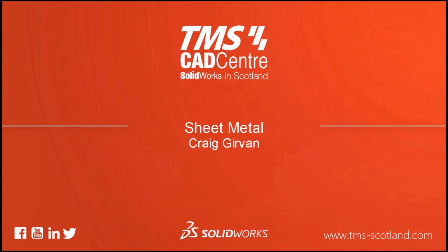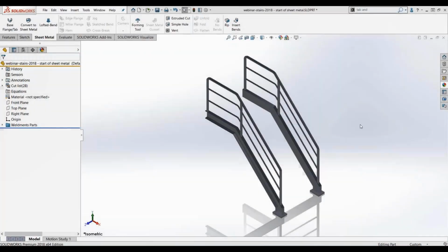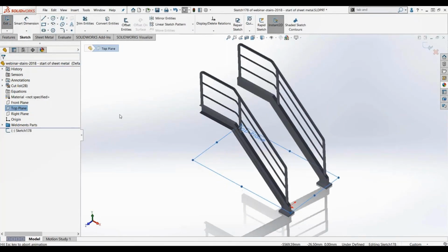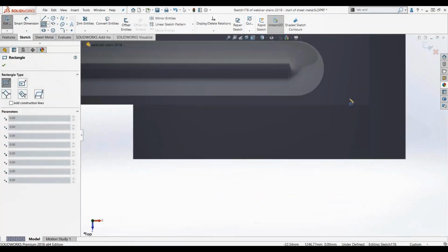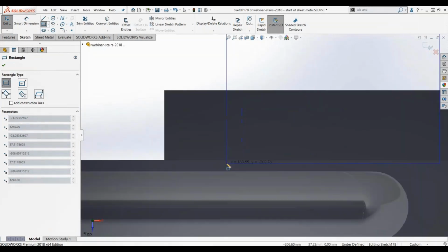So we've got the outside shell of it. Now we actually need to go through and literally add in the steps, no pun intended there. So what we're going to do is, once we have those side edges, we're going to first want to add in a base flange for our first initial step. So we're going to create an initial sketch, given that outline, making sure the rectangle is connected to both the top and the bottom sides of those frames.